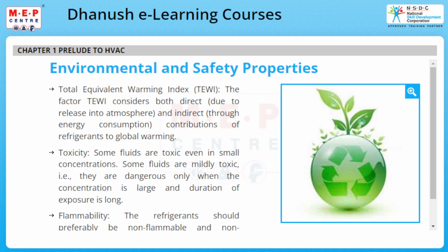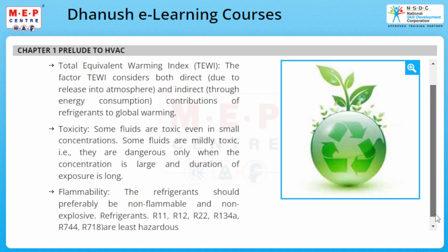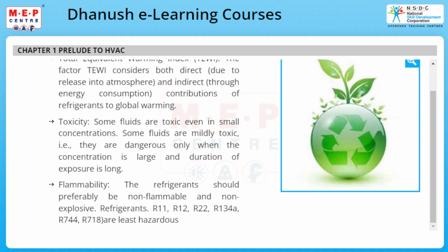Some fluids are mildly toxic, that is, they are dangerous only when the concentration is large and duration of exposure is long. Flammability. The refrigerants should preferably be non-flammable and non-explosive. Refrigerants R11, R12, R22, R134a, R744, R718 are least hazardous.